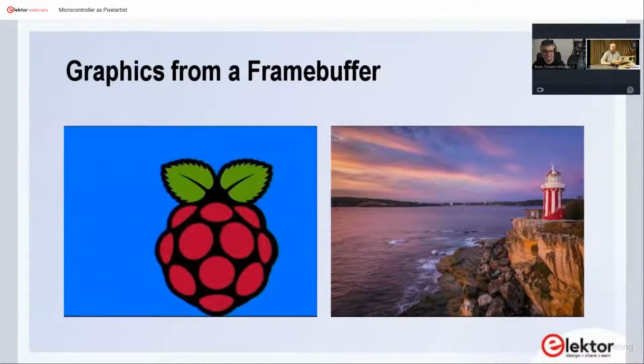The interesting point is, with the Raspberry, you can see there is a 320 by 240 image that's fully running out of the frame buffer from the RAM. The other one is a full-color 640 by 480 pixel image, and that shouldn't fit into the RAM of the machine. If you do the math, 640 by 480 by 2 bytes, you get a greater RAM requirement than the machine has. And there's another trick that the Pico has, and that's streaming image data from the SPI flash to the controller outputs itself. That's more advanced stuff, but it's quite nice to see that it's possible.